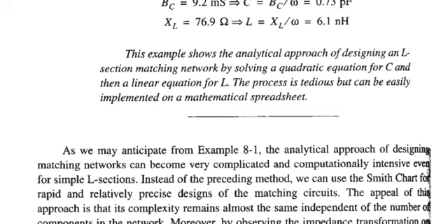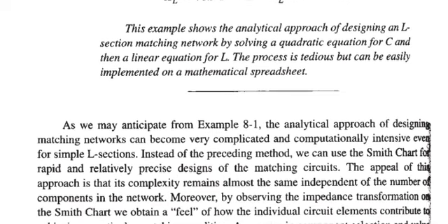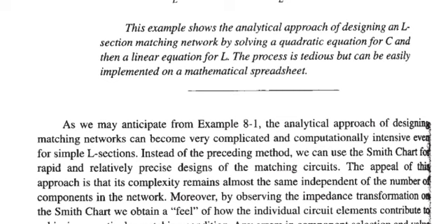I hope you have got an idea of how we do impedance matching just by using passive components, which are the inductor and capacitor forming your L section, and many possible combinations are available. You just have to find the value of L and C. In the upcoming videos, we can also discuss it with the approach of the Smith chart.